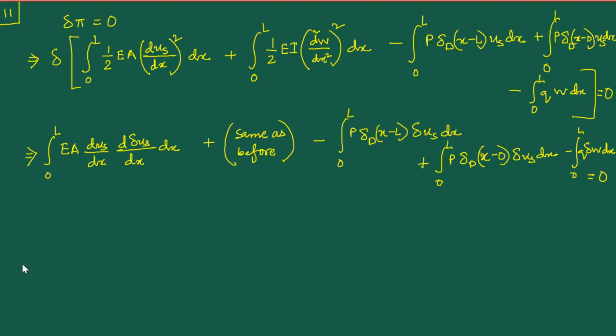All right. Now, all that I have not written here basically involves the various steps. If you remember from before, a repeated use of the integration by parts, and the motivation there was ultimately to arrive at an integration term which would involve the first variation of the bending variable or the deflection variable w, because in this other integration term we have this first variation of w which does not involve any derivatives.